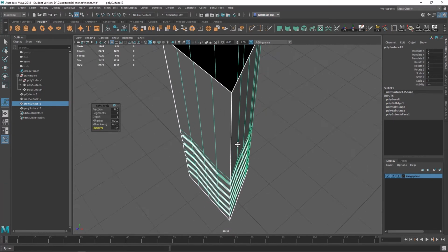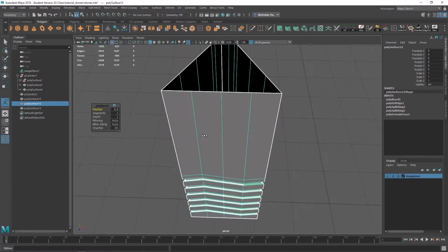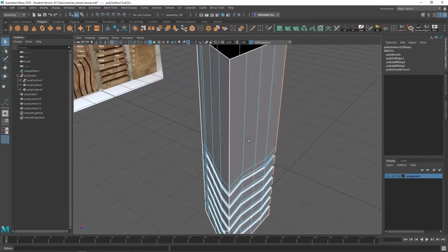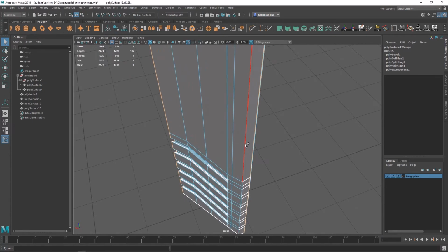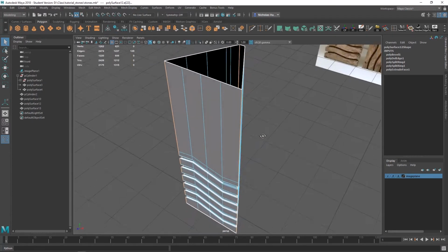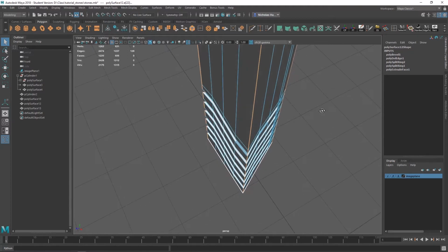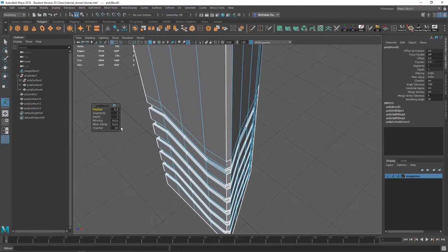Now we're going to see how the corners fall apart still. We're going to refine those. So you guessed it, we're going to go into edge mode, double click there, shift double click here, and shift double click this one and this one. And how do we define shapes better? We add more edges. What's an easy way to add more edges to an edge? Bevel. So we'll bevel, and I'm going to turn chamfer.